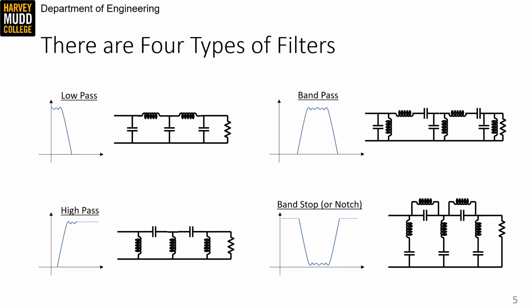Intuition for the bandpass and bandstop circuits requires thinking about the behavior of their LC tanks at resonance. Parallel tanks ring open and series tanks ring short, so the bandpass will have series short circuits and shunt open circuits at resonance, which allows voltages to reach the load. Off resonance, either the inductor or the capacitor will block signals in the series elements and absorb signals in the shunt elements. It's worth noting that all the filters on this slide are third order.